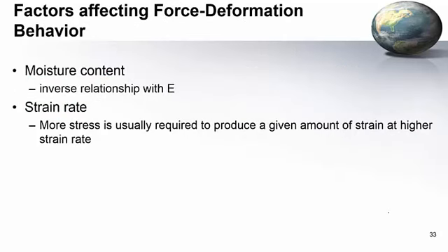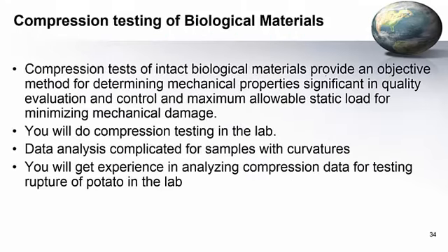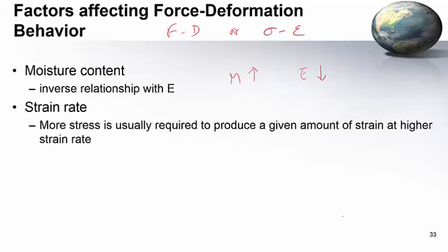The force deformation behavior or the FD behavior or the stress strain behavior, it is related to moisture content, right? So typically the moisture content has an inverse relationship with the modulus of elasticity. Higher the moisture content, the lower the modulus of elasticity.